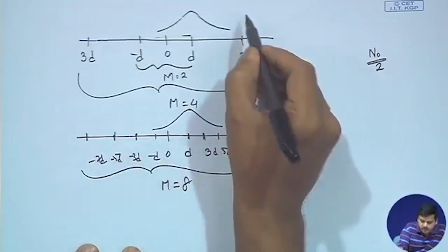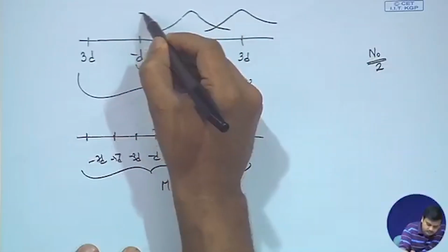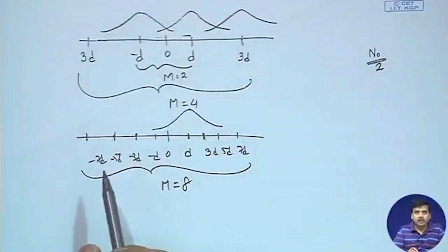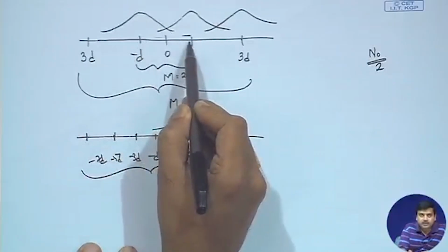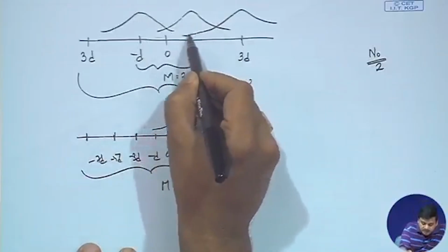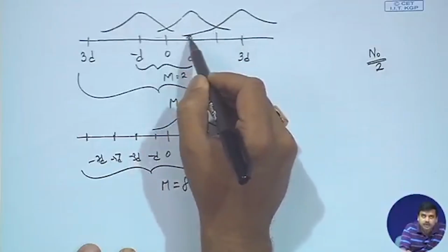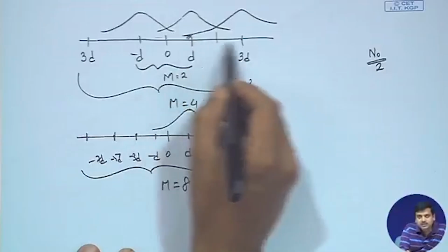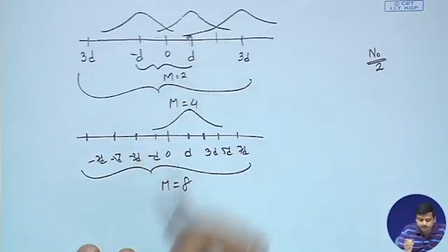So, if the variance of noise has remained the same, the way you could keep the error probability the same is by maintaining the same minimum distance, because you are interested in calculating the area under the tail probability, right. Which will remain the same if this distance is kept constant, that means this area is remaining constant.